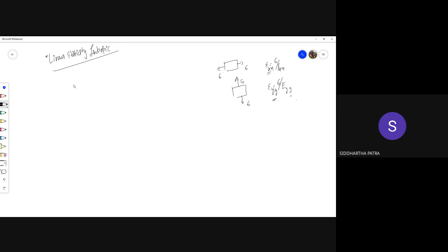Now, in linear elasticity with isotropy, this is how you can represent the general relationship between stress and strain. And this representation is necessary and sufficient. I'm not going to prove the necessary part of it. Of course, there is a proof in any continuum mechanics book, but I'm going to show you that this is sufficient, that this makes the material linear, elastic, and isotropic.